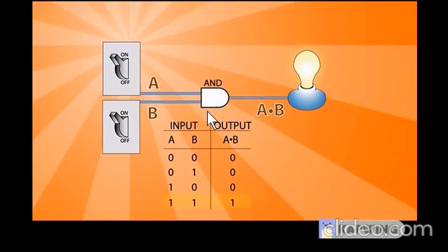So you want to operate this fire alarm only and only if a smoke detector and the fire are both in high conditions. Means in normal condition, when it detects a smoke, it should not work. So what is an engineer going to use in that condition? The engineer will use an AND gate. So only when the fire thermistor turns high and also the smoke is detected, then only the fire alarm will work. So you understand the simple application of these circuits?